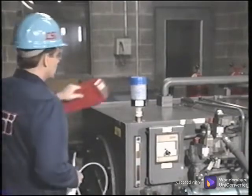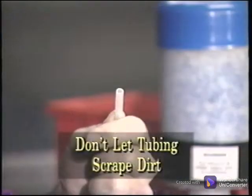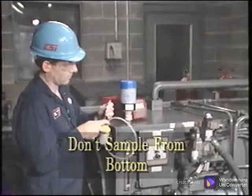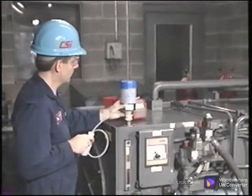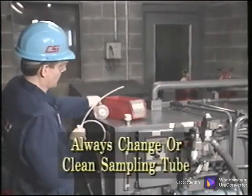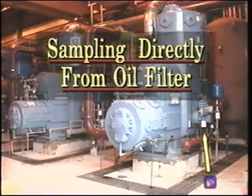When using a suction pump to draw oil up from a sump through a fill pipe, dipstick tube, or other orifice, don't let the plastic tubing scrape dirt from outside the orifice or from the bottom of the sump. On the other hand, if you are concerned about free water in the system, go ahead and sample from the bottom of the sump. But remember, always change or clean the sampling tube between samples. As a general practice, you would not want to initiate a maintenance action on the basis of an oil sample taken directly from a used oil filter.